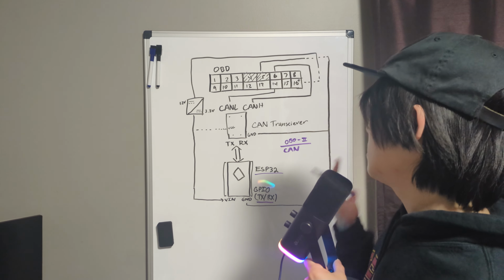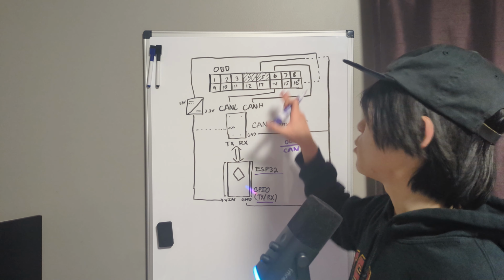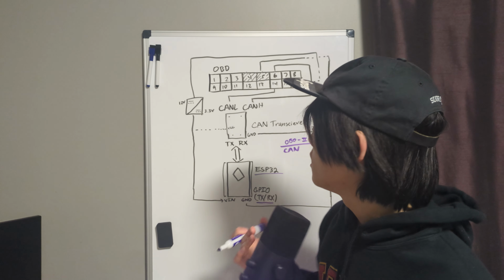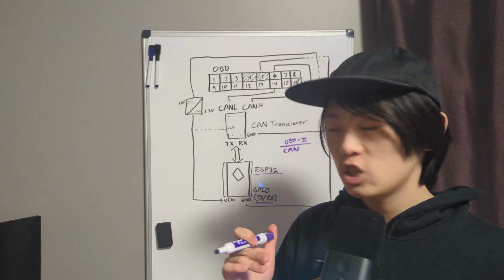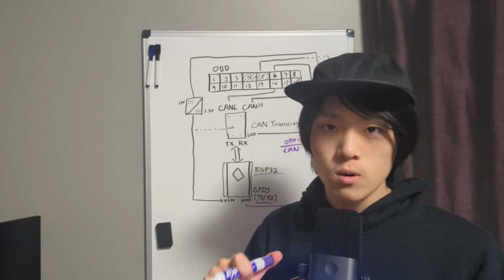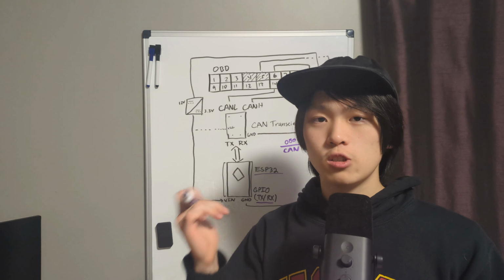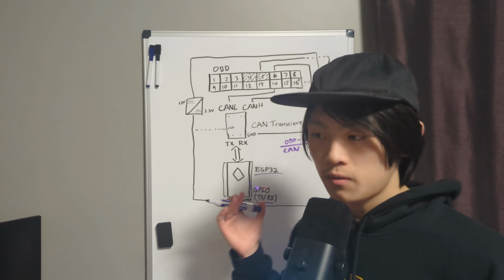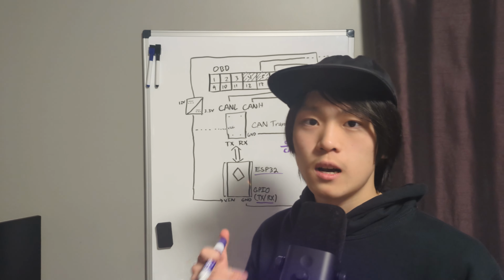And if you look up any specification of the OBD port, you'll realize that a lot of these ports are vendor specific, meaning that it depends on the specific manufacturer of your car. Thankfully, with the CAN L and the CAN H, which sit below the OBD2 protocol, the idea of the OBD2 protocol is to offer a standardized way. A standardized way meaning that anyone with the standard can implement their own reader or writer, and their own tools.